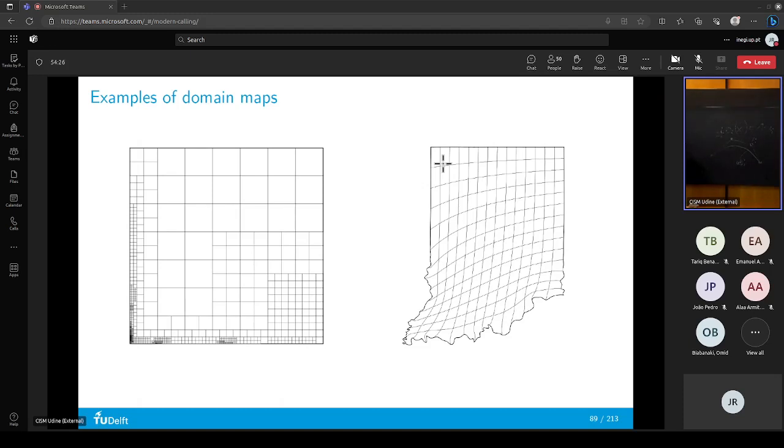There is not really a, well, what you can do is use, I think it's called Cubit, a kind of mesh generator. A mesh generator that gives you a coarse or macro mesh with quads or hexas, because technically what we need are only quads in 2D and hexas in 3D. What many different groups do, also what I do in my group, is application-specific meshing, or say blocking and then meshing techniques.